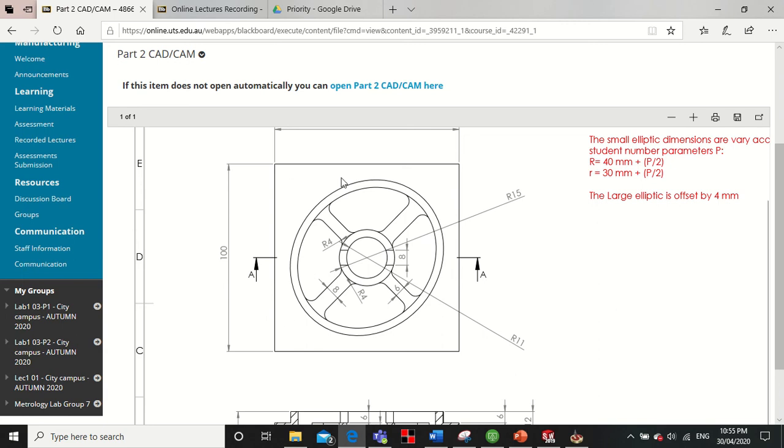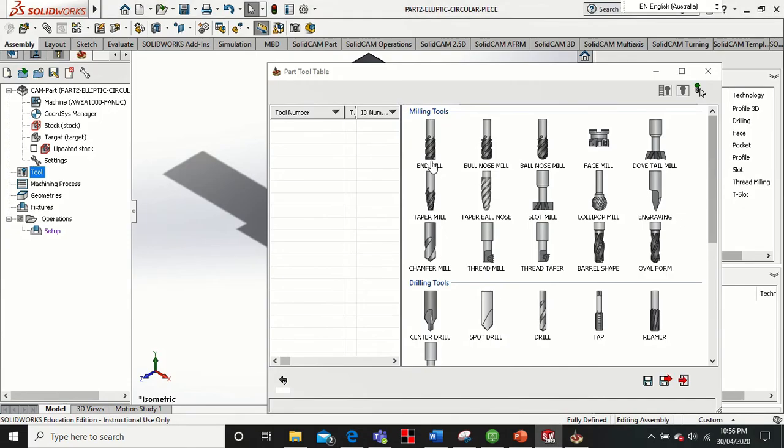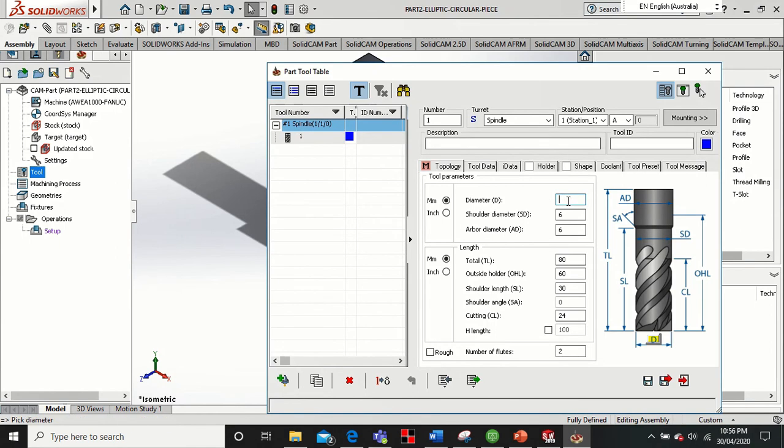We're going to choose the first tool by observing the different physical characteristics in here. We're going to be working on the outside surface first, where we have the sharp edges and the circular face. For this, we're going to be using an end mill, 10 millimeters, which is recommended by many operators doing CNC, to not have excessive chip load or any other characteristic that could be implemented into the process, but we're mainly focusing on the toolpath again. So we're gonna save that.